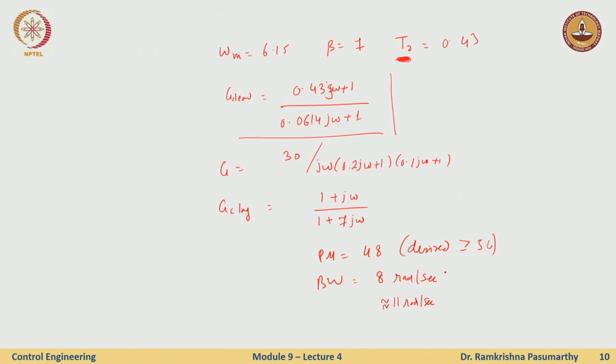Now see the steps involved. With the lag compensator we had some partial compensation, where the closed loop, gain compensated system with the lag compensator was stable with a decent enough phase margin. We are still far away from what is desired. Now I can use a lead compensator to increase the bandwidth and also push up the phase margin.